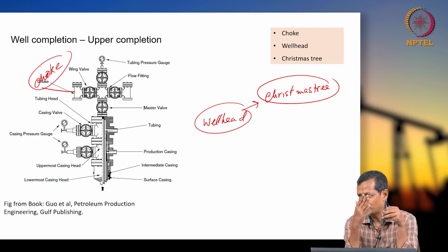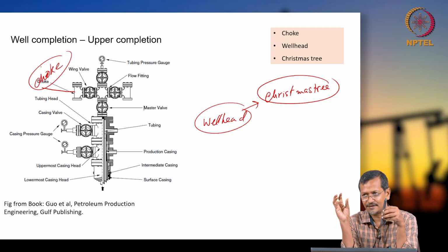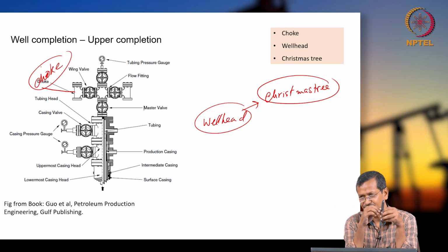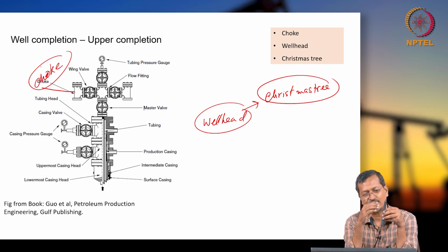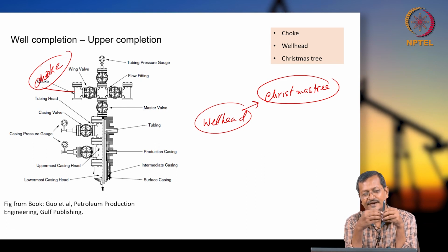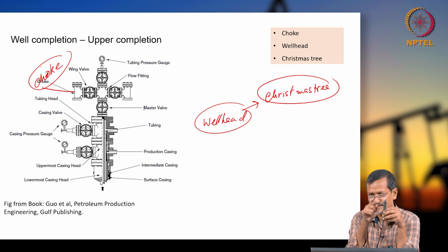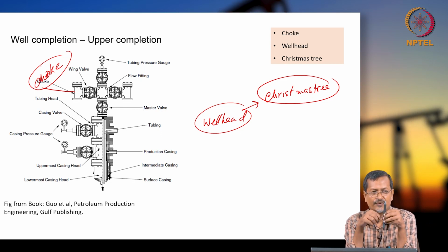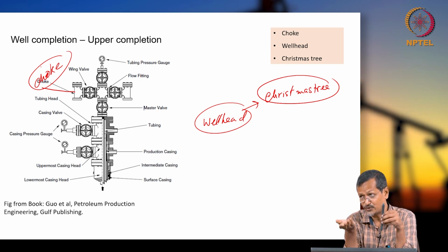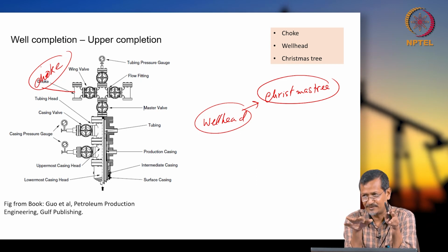Softer material will get removed quickly, and the corrosive fluid will again get a fresh surface. So it will say, okay, I got a fresh surface, I will act again. So it will create salt again, again metal hitting. So corrosion and erosion will erode the system quickly. That will be more dangerous if you have corrosive fluid and erosion also occurring. So you have to prevent both if possible.